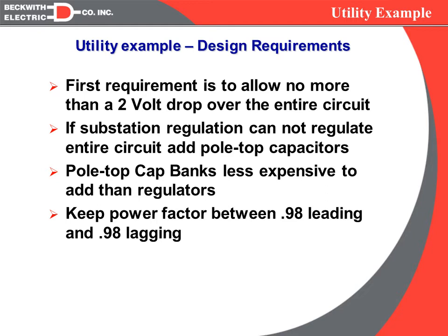Their next goal was, if the substation LTC cannot, and even if it could regulate the voltage, to let the capacitor banks regulate the voltage. So we're going to install switched capacitor banks, and we're going to let them be the primary regulating device. So we're not looking at a capacitor bank as a power factor correction device, but as a voltage correction device. And we want to keep the power factor between 0.98 lead and 0.98 lag.